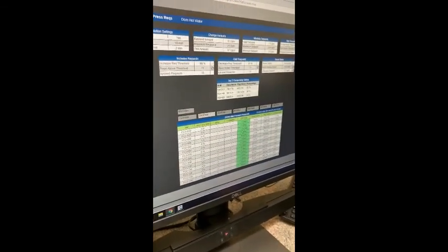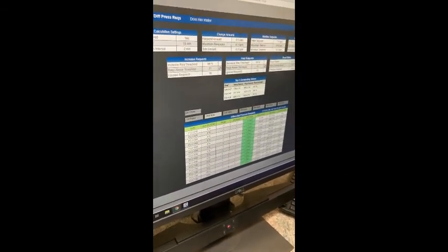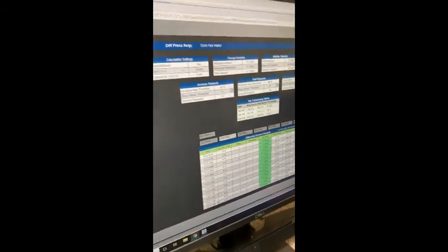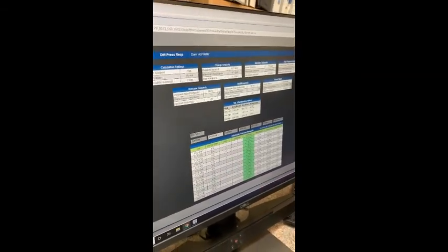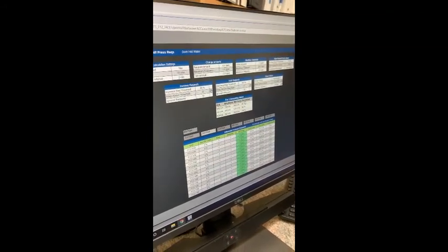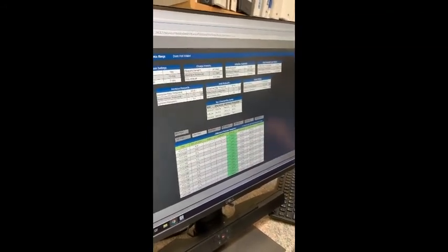It will keep track of who's been calling for it the most, basically your worst perpetrators of needing more. If it's way out of the ordinary, that means there is probably something wrong with it. Even if it is working and maintaining temperature, there could still be something wrong: the hand valve may be slightly closed, the actuator may be failing but hasn't failed all the way, or it could be clogged up. It tells you, hey, these are the ones you'd want to take a look at.